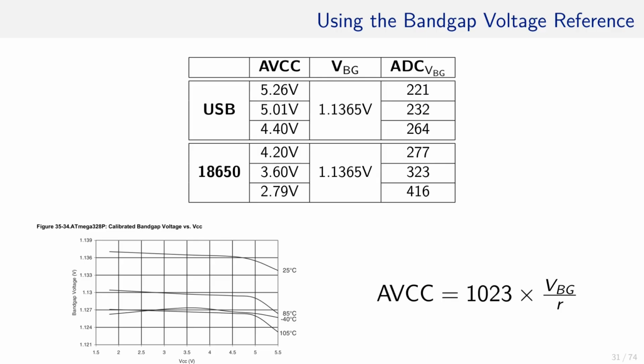Therefore, and as a bonus, if let's say the ATmega is powered by an 18650 lithium-ion cell whose operational voltage range is between 4.2 and 2.8 volt, this measurement tells me how much juice is left in the battery and if it should be recharged or replaced. Especially lithium cells are quite sensitive to undercharging, and hence these readings allow the developer to mitigate damaged batteries.